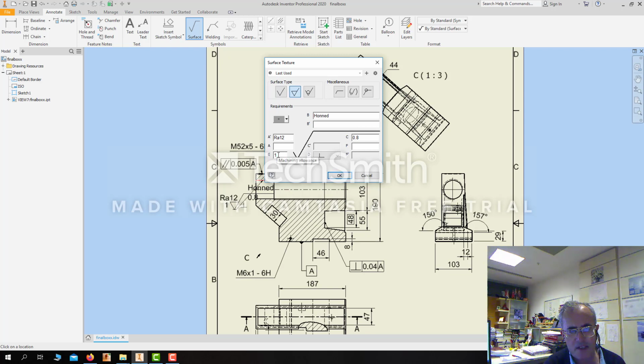Into this box write the machining allowance. In some cases it may be important that the object at the beginning of the finishing process has such an extra material. From the starting surface to the finishing surface, the shortest distance is the machining allowance. It is written into this box.